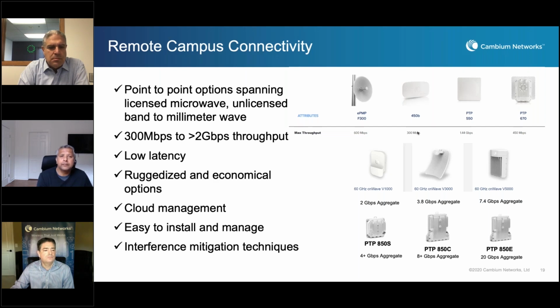A question just came in about FCC. Do they need to have FCC certifications to deploy these wireless solutions? Right. Good question, Jonathan. Technically, if you think about what your Wi-Fi stuff operates in, you don't go and ask the FCC for permission. So essentially, that entire 5 gigahertz band is a lot of spectrum that does not require any type of FCC certification.